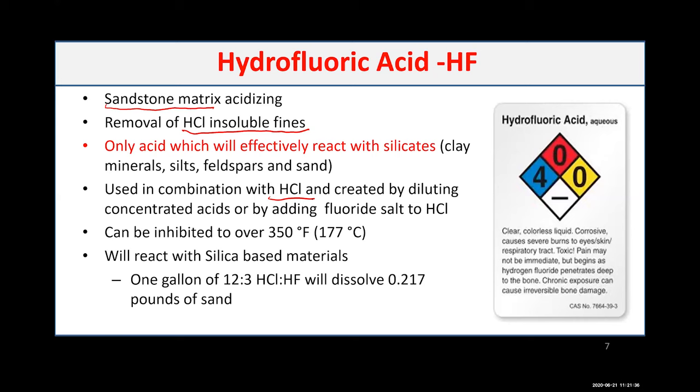Therefore, when you are talking about sandstone acidizing, you need to be really careful about how you're designing your job. What's the post-flush and pre-flush that you're pumping, and how you're pumping your job. And definitely, don't pump HF until you are extremely sure that you have a damage that needs to be removed by HF.